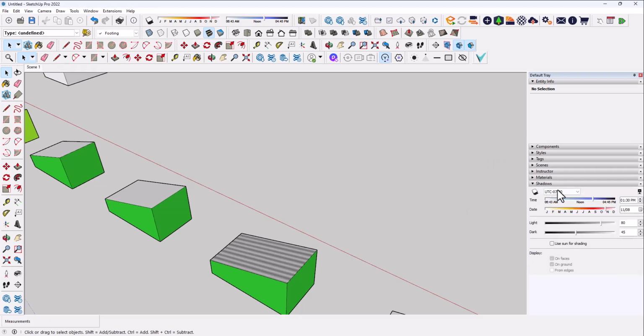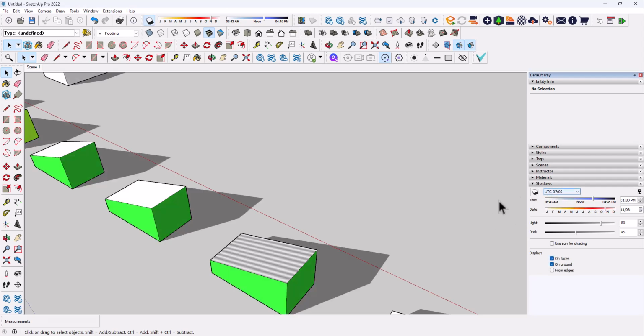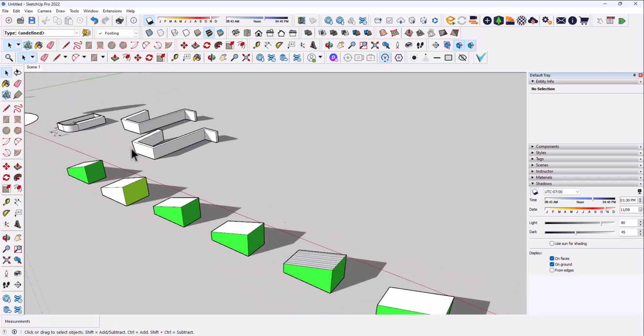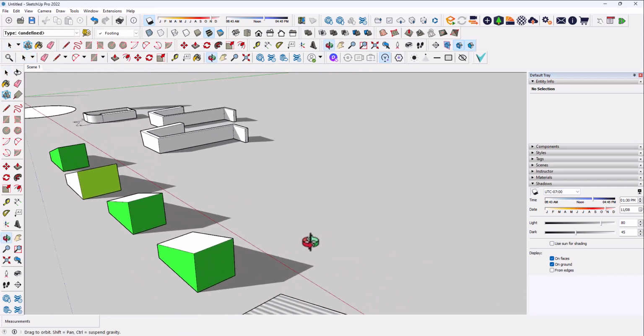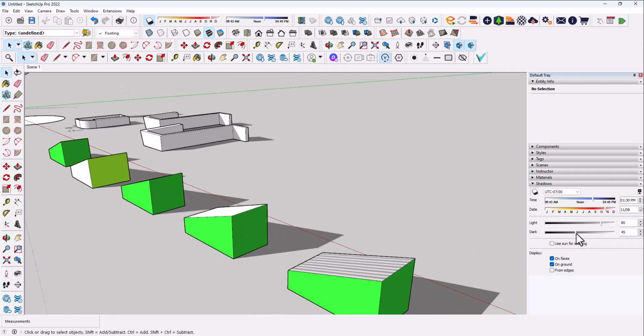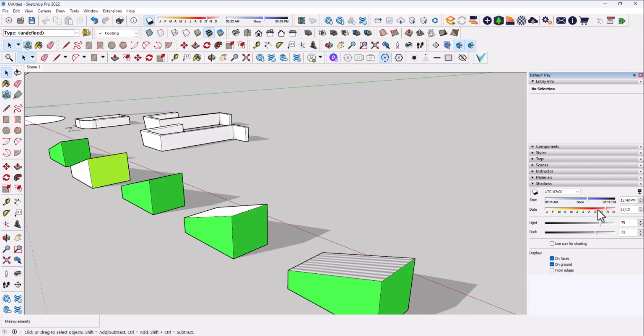And then this last part, shadows. So we can turn shadows on by clicking this show hide shadows. And now it's giving us a preview of what this view looks like with shadow. And I can change the lightness of the shadow and how bright the light is, kind of the spotlight hitting the geometry. And I can set various days and times. I can give this project an actual location up here, so give this an actual geolocation so that all of this is accurate.